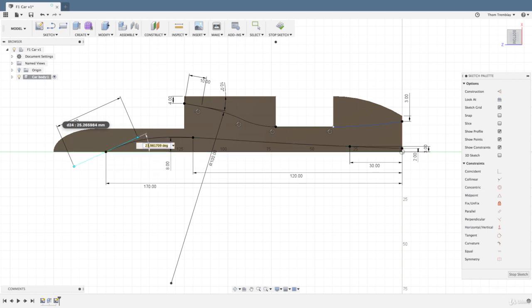Then I'll select the line again, and then the center line edge, and set an angle of 20. And when I press enter, watch how the curvature responds. Brings the curvature back in a little more smoothly and a little more closer to the center line between the first and the second points. For now, that's all the control I want to apply to the spline. You can always add more at any time.